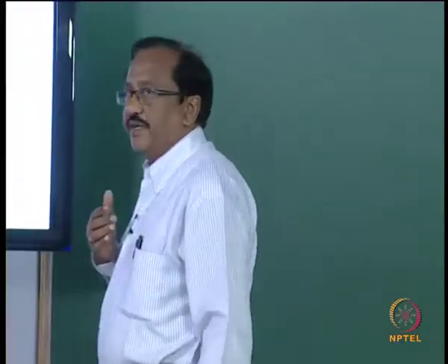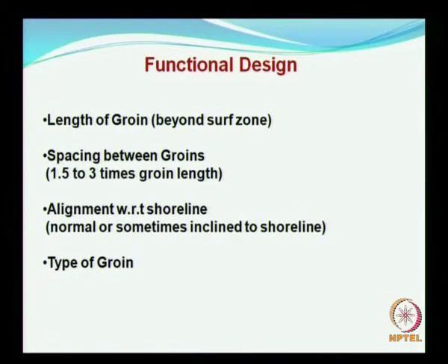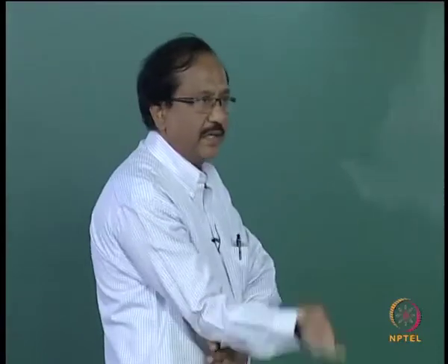Functional design. The length of the groin, as I have said earlier, has to pierce the surf zone, that is very clear. The spacing between the groins should be between 1.5 and 3 times the groin length, and alignment is usually perpendicular to the shoreline, but sometimes it is slightly inclined. And also the type of groin, it can be a straight groin or an inclined groin or a T groin, etc., we will see later.